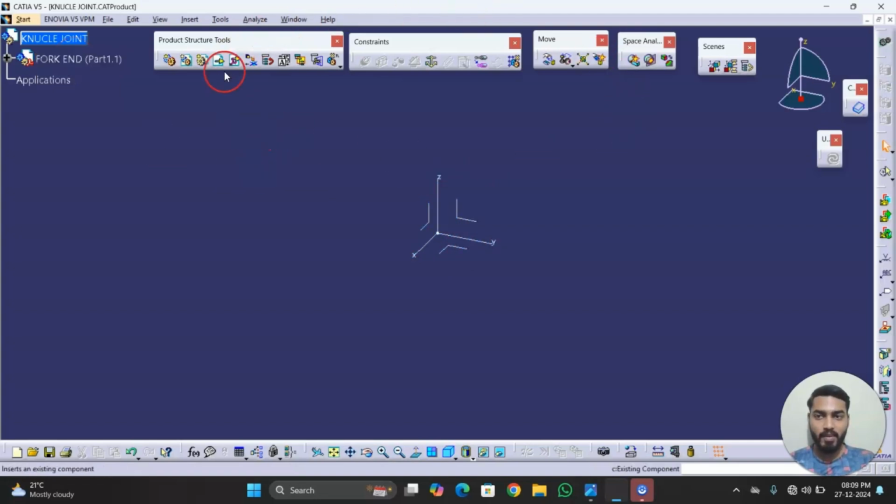Usually we are in assembly design. You can see all these toolbars. Now from assembly design, if you want to enter into part design, we need to open this component which is under this assembly design. Then again if I open this, this is the part we have. Identifying these icons is very important. If we have a single gear with this blank sheet, that is nothing but a part design.